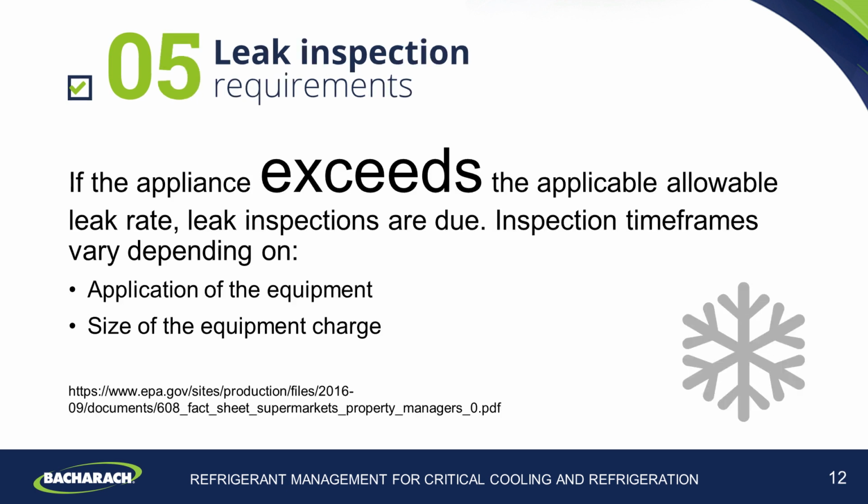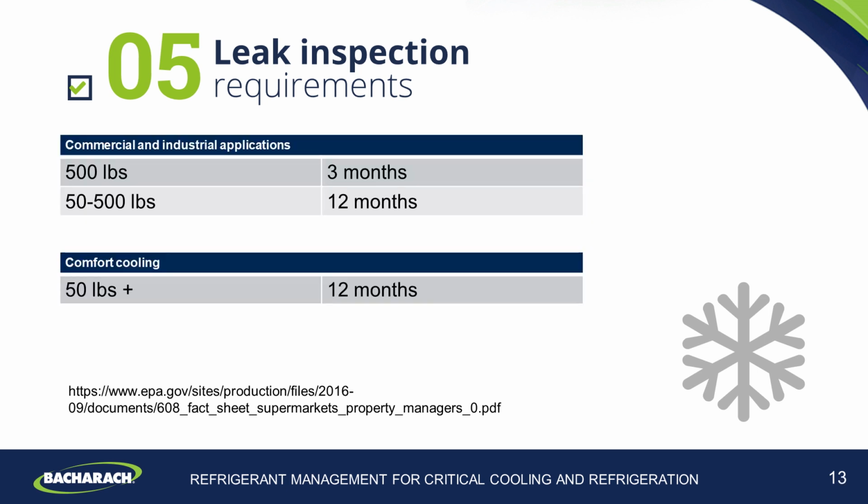For point 5 on our checklist, let's get into the leak inspection requirements. As we discussed earlier, if the appliance actually exceeds its allowable leak rate, then we need to get into some additional requirements, and these requirements are inspections. We'll have different inspections depending on what type of equipment it is and also the size of the charge in the equipment. So here on the slide, we can show you what the sizes are and the time frame